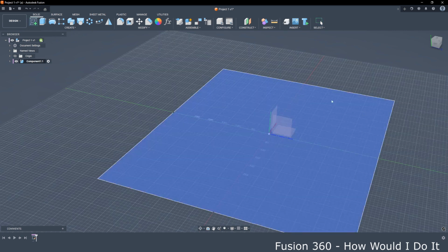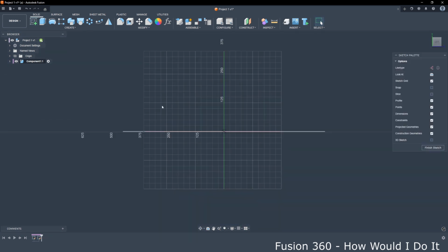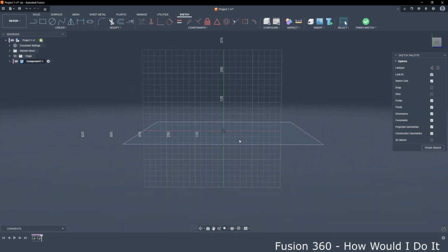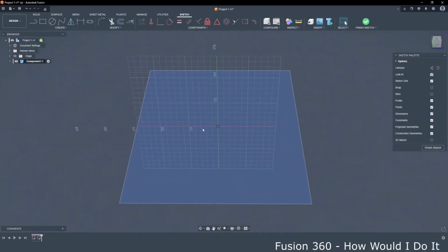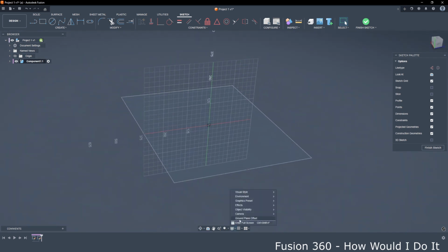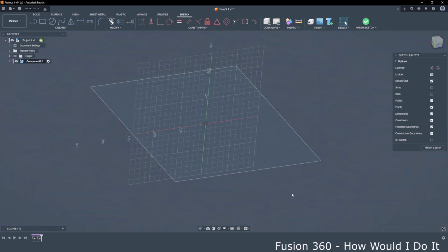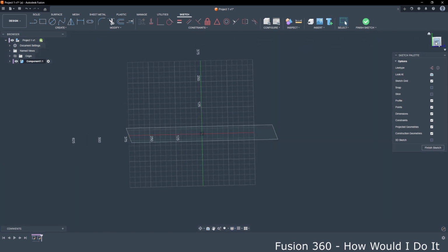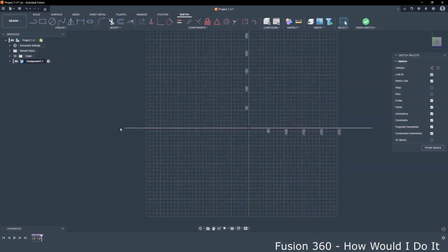Now create the second sketch. Now since I have here a perspective view, I will try to have orthographic view here, and so you can change that in display settings, camera, orthographic perspective, perspective with ortho faces. Now I will create another sketch.